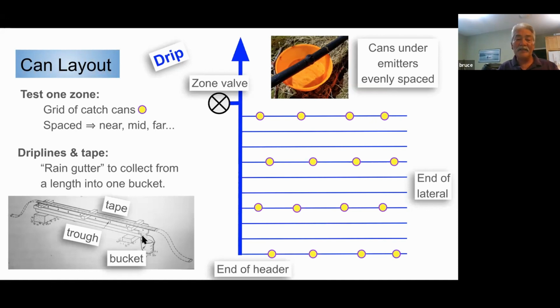I would rather see catch cans placed finer along a given line in 2 or 3 different circumstances. Take that, multiply it by the number of emitters to determine the flow of the whole row, but you still have that ability to see how uniform each emitter along that line is. So yeah, the whole flow of that line, you want to know exactly what the contribution from emitters in parts of the line are.